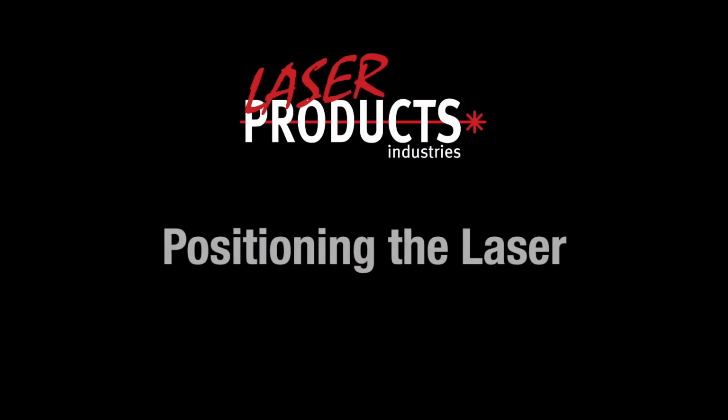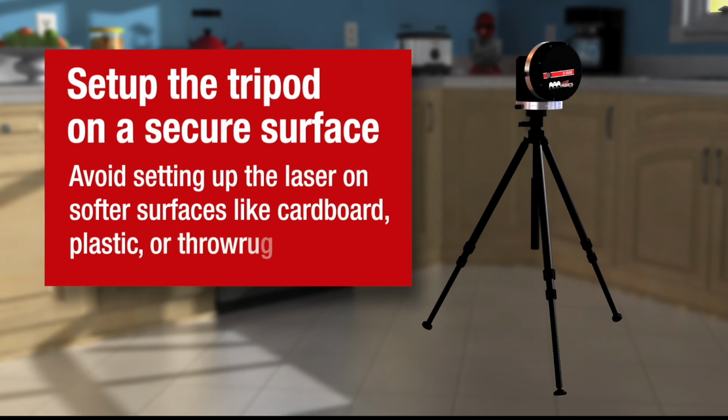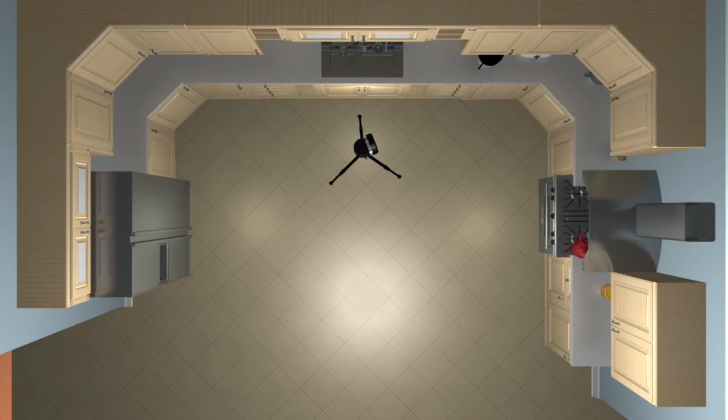In this video, we will be covering laser positioning. Make sure the tripod is on a secure surface, as the laser system needs to remain stable during the entire templating process. In most instances, you will want to set up in front of the sink or the cabinet sink center. This allows for the best angle for measuring the sink center and countertops.